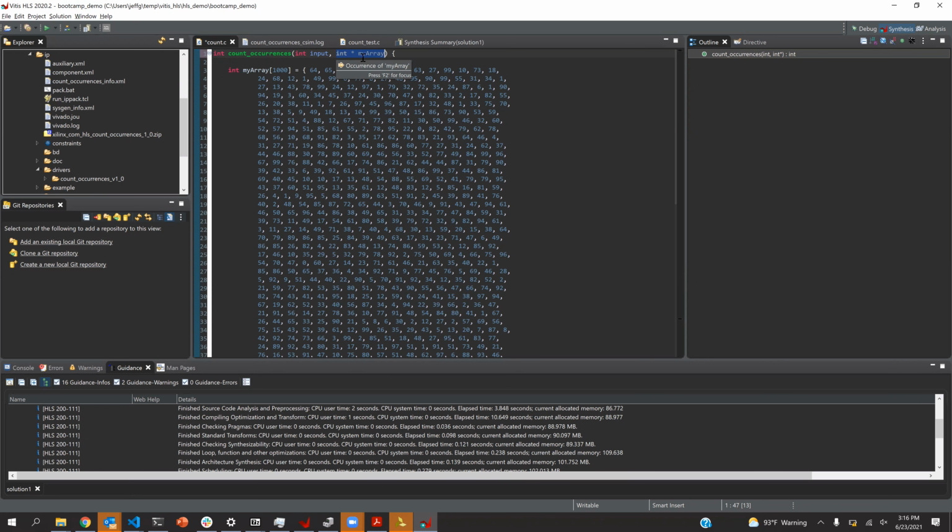But the main memory is much slower than the DRAMs on the FPGA. I don't know, Hayden, do you remember when you moved out to main memory, how much slower was it? 10 or 100 times or something, like, yeah, 10 times slower. And you can't do any unrolling at that point. There's just one DRAM. You don't get to unroll it and say, oh, we're going to split this across like 10 or 50 VRAMs. No, too bad. You get the access to main memory just like the processor does, and so it slows down a lot.